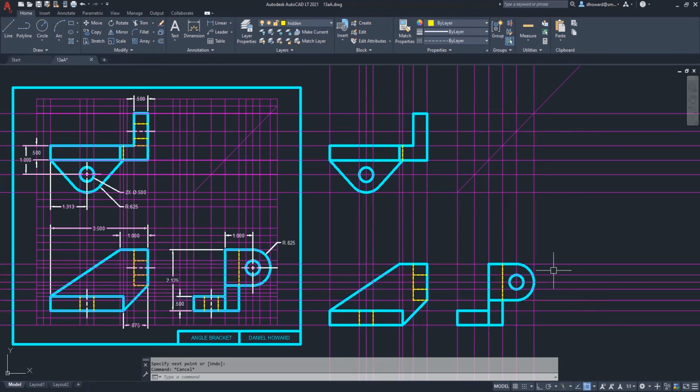Whenever you get a perfect intersection, it always brings suspicion to it because you're like, what is that? That's not how it's supposed to be done. Center lines either go long or they go short. And you can see that's what I did over here. That's why these are short of the line.